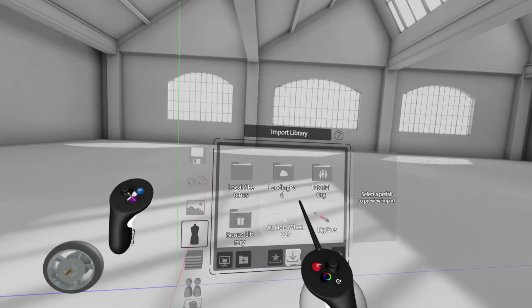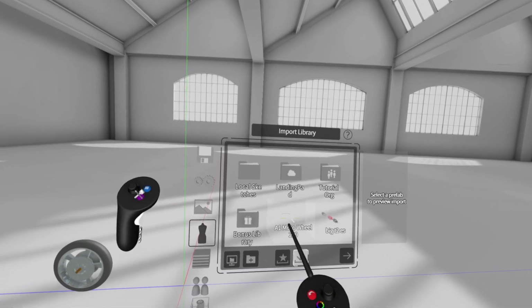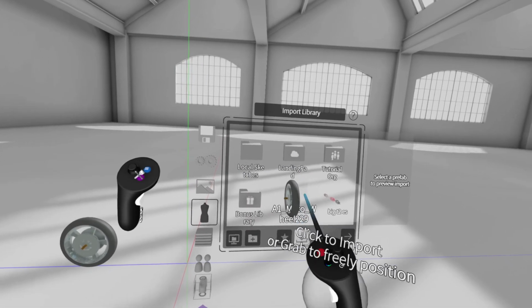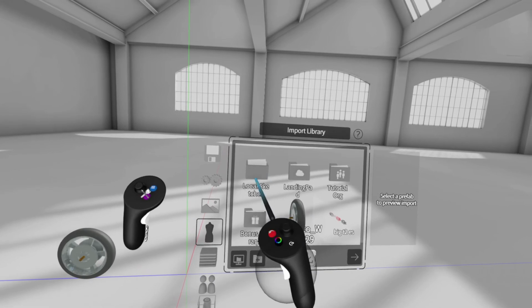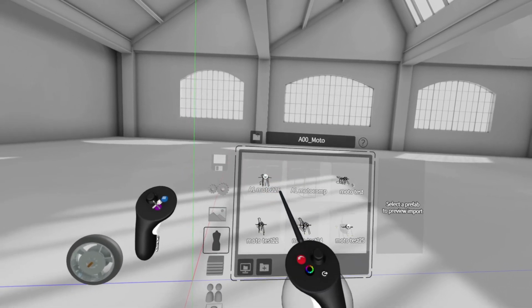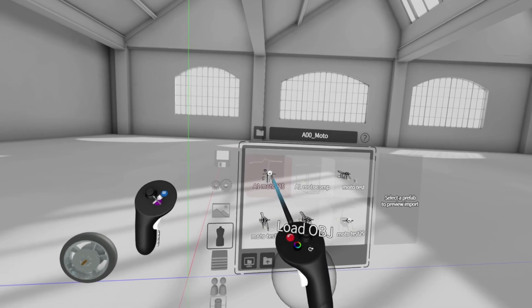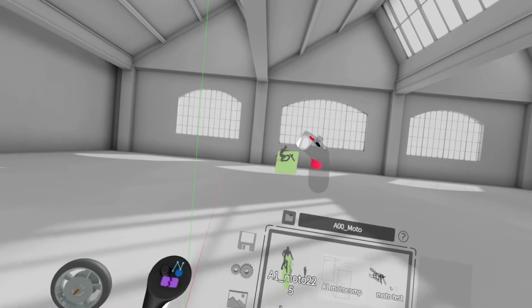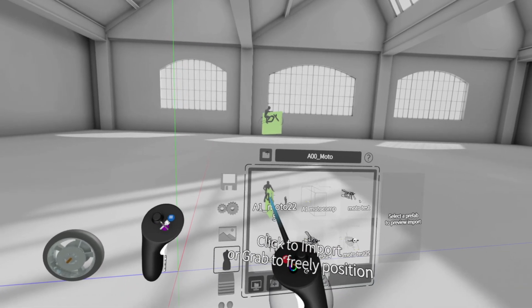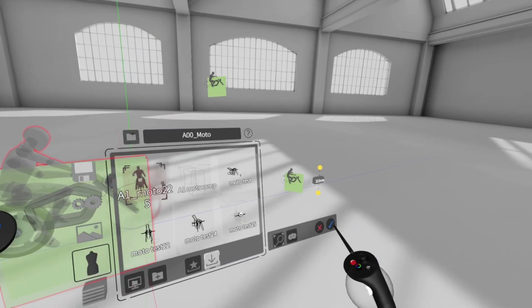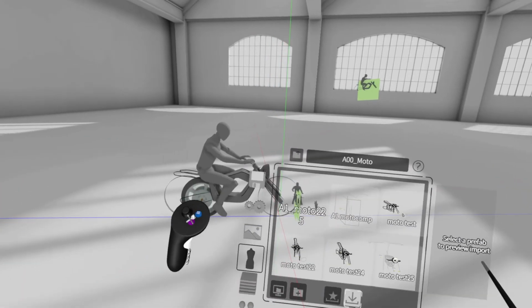Your third option to work with one of your files in co-creation is to use the import function. While in the co-creation space, press the blue button to open up the Options menu and then open up the Prefabs menu. Next, press the import icon indicated by the arrow to open up the import library. Here, you will be able to import files from your device or from the cloud. For example, here is a prefab we made earlier. You can also navigate to the file you would like to import and press on it to load up the file. Once loaded, you can either drag the file into your scene like this, or point on the file one more time with your drawing hand to load up a preview. Once happy with the preview, press the blue check mark and the model will be imported, along with the layer structure of the model.